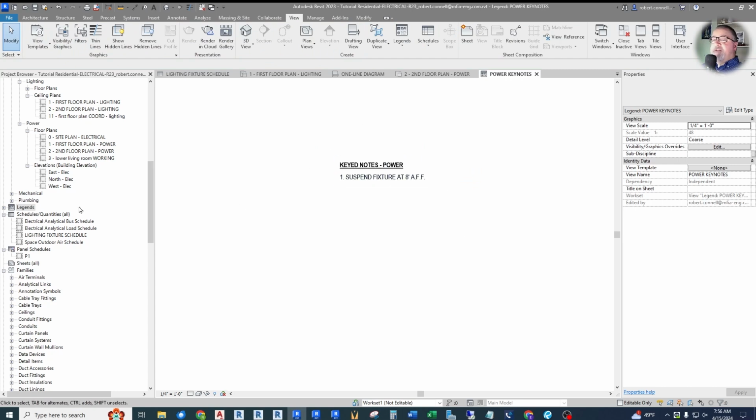Now, this legend we can actually drag onto a sheet when we get into creating our sheets. But this is a way that I like to create my keyed notes or keynotes rather than just typing them onto the view or onto a sheet, because then you can rearrange them and you can use them multiple times. So I just wanted to show you that's how we are going to handle keyed notes on this project.